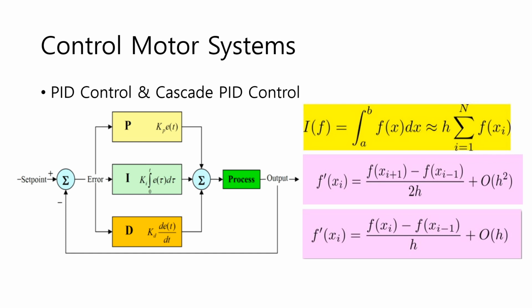To implement PID control, it is necessary to utilize the derivative and the integral of the error. We use the backward difference and rectangle method to calculate these with minimal computational cost. This will increase our iteration frequency and will have a noticeable improvement in control performance.